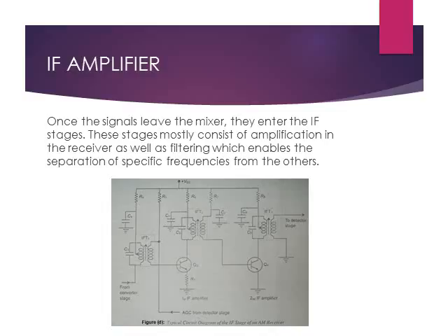Now let's see what an IF amplifier is. Once the signals leave the mixer, they enter the IF stages. These stages mostly consist of amplification in the receiver as well as filtering, which enables the separation of specific frequencies from others.